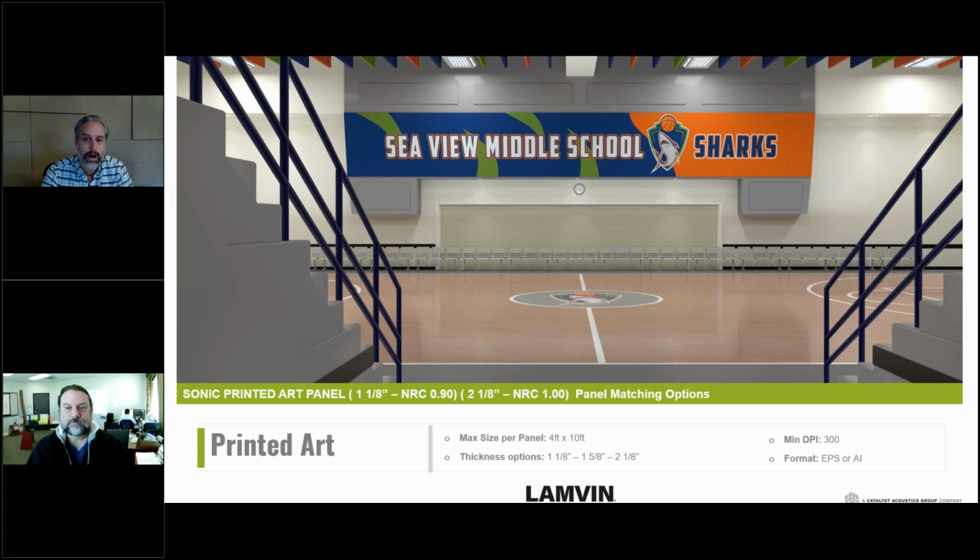And then what we also offer, and what Rick and his team do, is when we're laying out our shop drawings, we will put guides on the back of the panels with a lettering system to let the installers know exactly how it needs to be put in. If we have multiple patterns coming through like this, you have to know the order of the orientation, or it can be very hard for someone to just look at it and know exactly how to install.